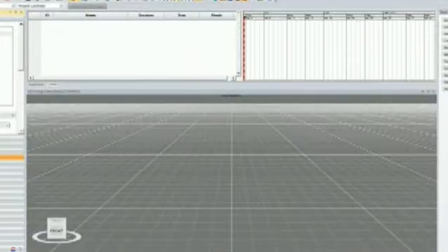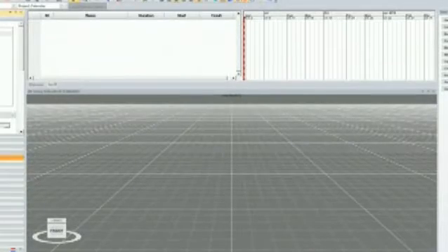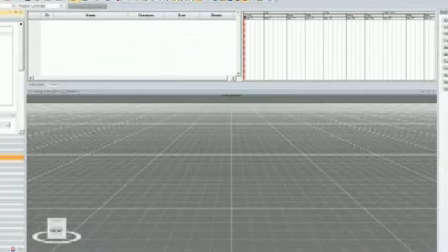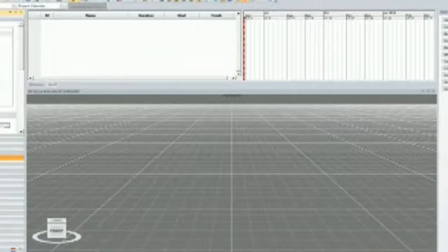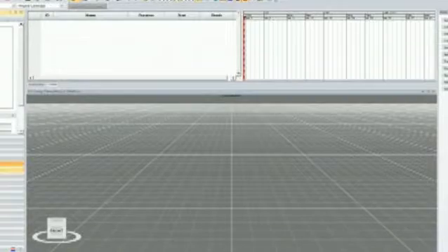Use profiles are, if you want to do cement work or concrete, you can create profiles that are formwork, rebar, pour concrete, strip forms. We can do that via color and transparency of the CAD of the objects in the model. We'll go through some of that later too. External data, what we brought into the model.